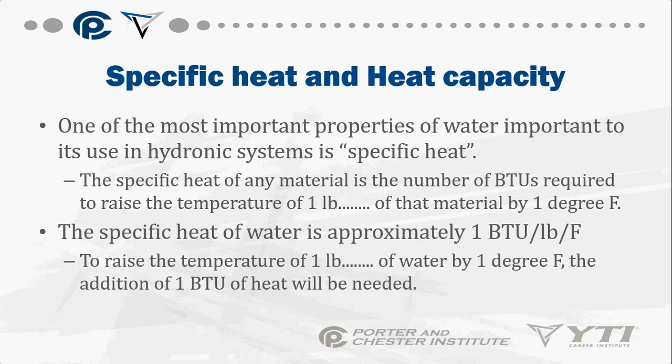Specific heat of any material is the number of BTUs required to raise the temperature of 1 pound of whatever that substance is 1 degree. What is that also the definition of, guys? BTU. The definition of a BTU is the amount of heat required to raise 1 pound of whatever it is 1 degree.